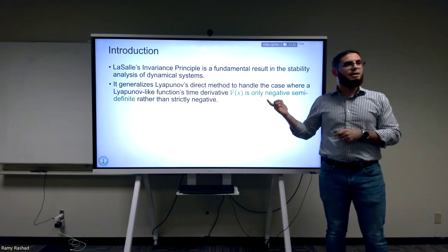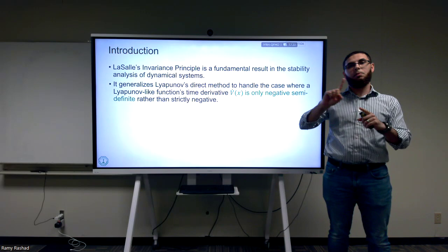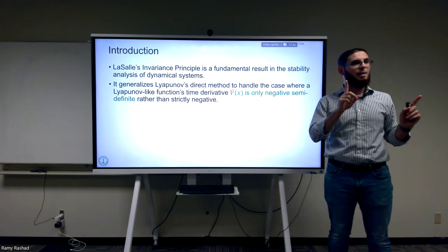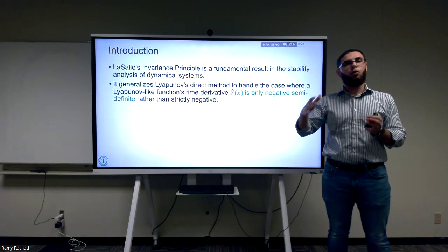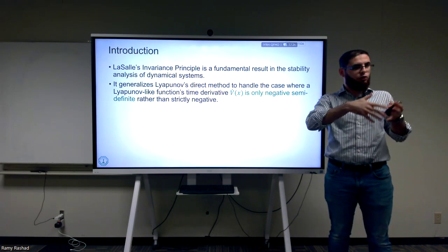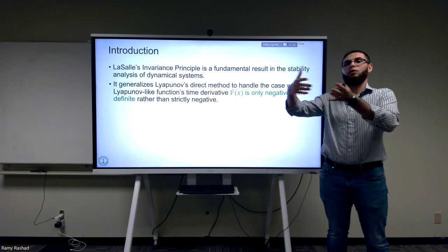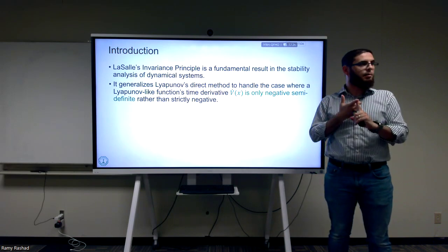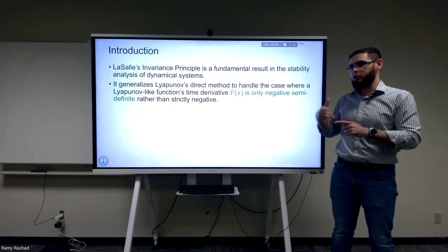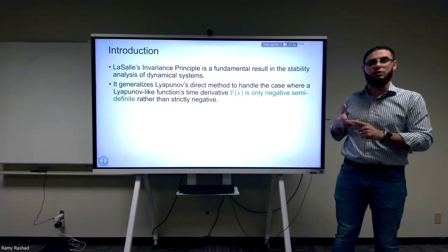The best thing about Lassalle's invariance principle, first of all, is that it's not something alternative to Lyapunov's theory, to Lyapunov's direct method. It's actually something that's augmenting. So when you do Lyapunov's direct method and then you want to extend it further, you can use Lassalle's invariance principle. So this is one nice thing about it. It's not an alternative theory. It's just some extra results, some extra analysis you can do.